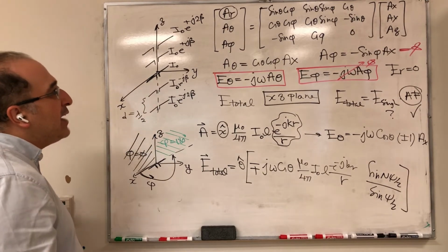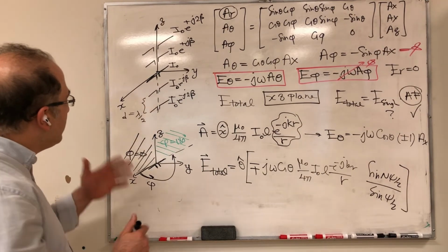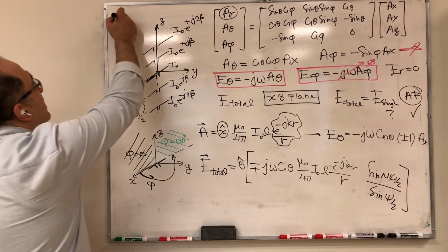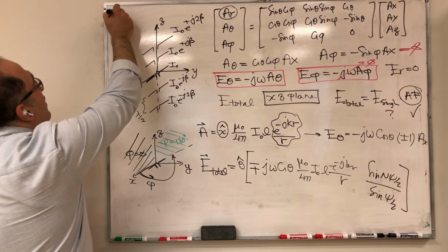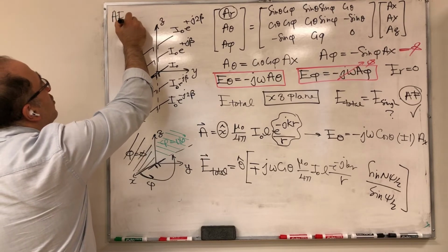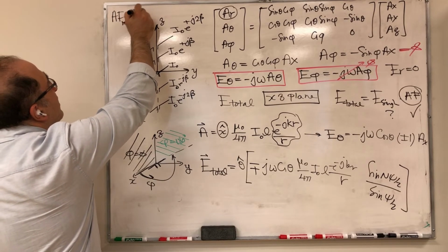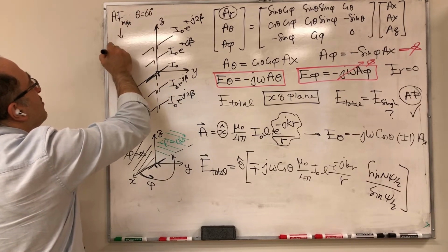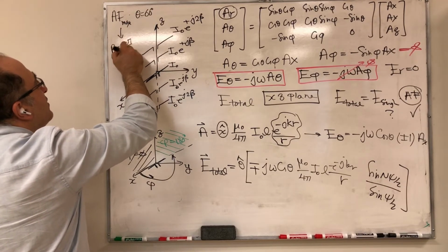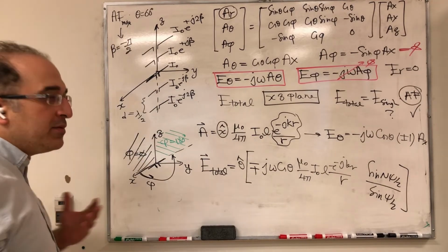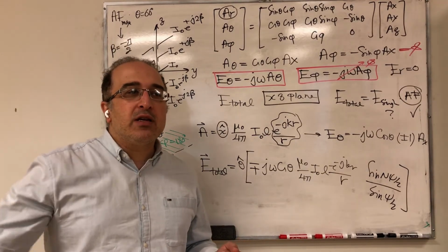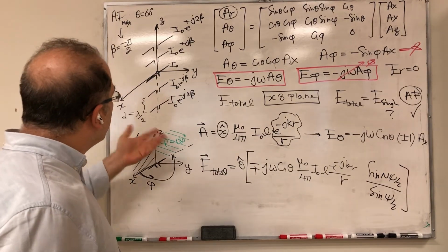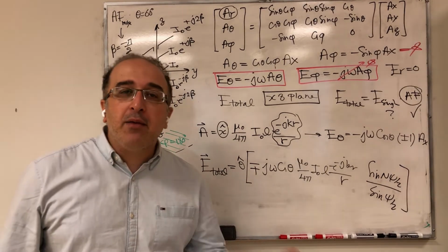Now imagine that we find everything as in the first part of the question. In the first part of the question we said we want the array factor maximum to be at theta equals 60. Based on that we found beta to be minus pi divided by 2. Now I'm saying, let's assume that, for example, the person who's fabricating this or creating this antenna makes a mistake.